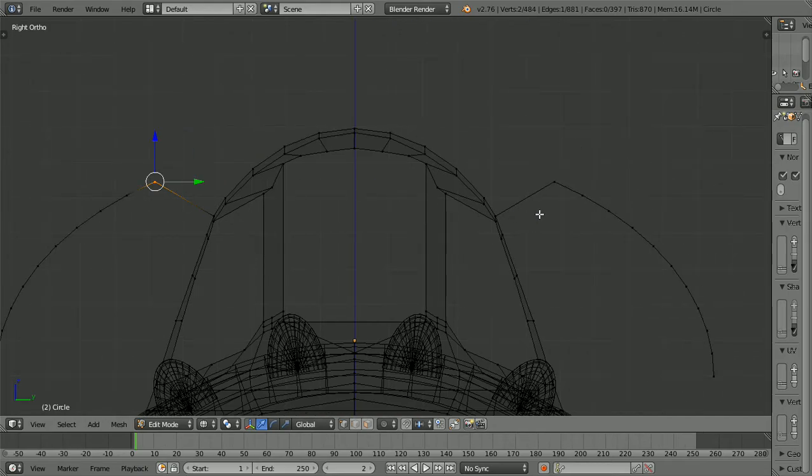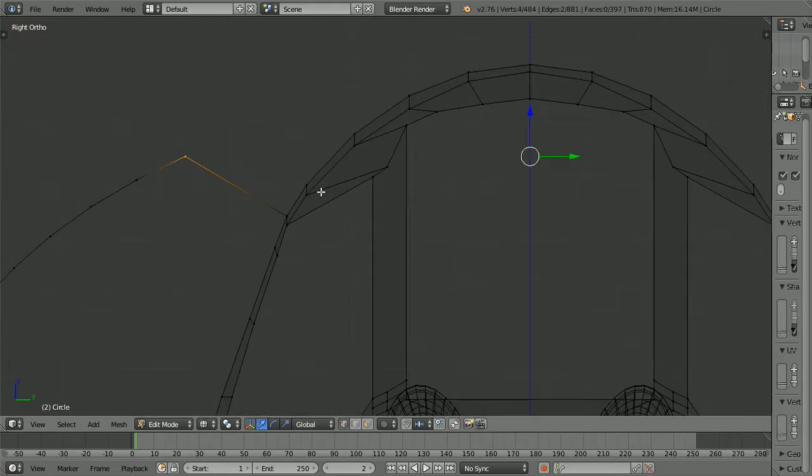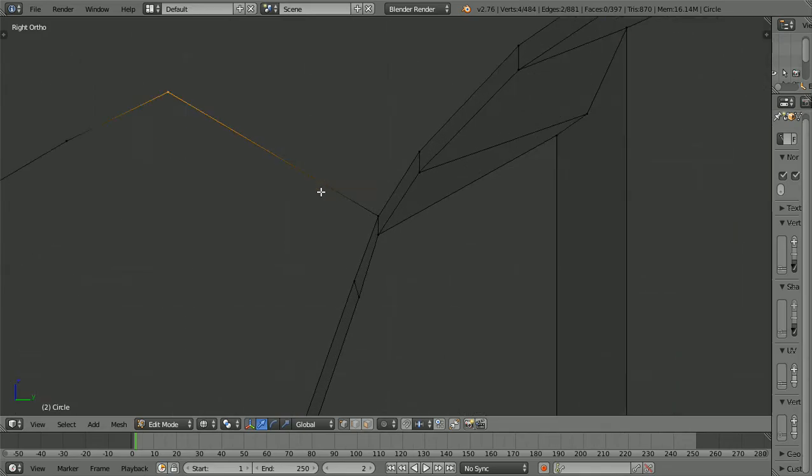And there's been some things I've drawn the hard way. I was drawing some gun turret stuff for battleships, and I was drawing a whole bunch of stuff at angles. And then it dawned on me, the more you can draw stuff straight up and down and horizontal and get it shaped and then angle it, it works way better than trying to draw it at angles, especially in 3D. Okay, let's grab this to the Z. Let's bring it down. Let's scale it to the Y.